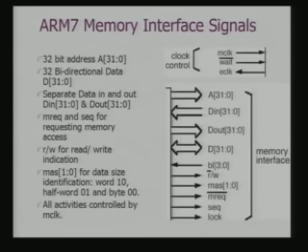A very obvious thing would be that if you are just putting in a ROM, a non-volatile storage where you do not need to write, you may connect it directly onto the data in bus, and if you are connecting a RAM, that would typically be connected to the bidirectional bus.